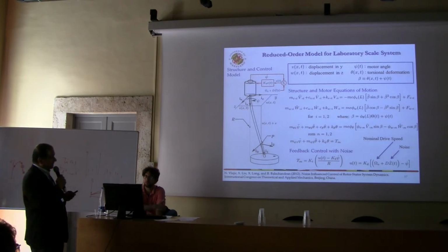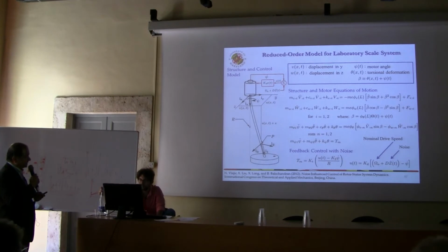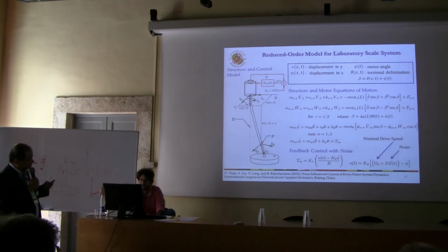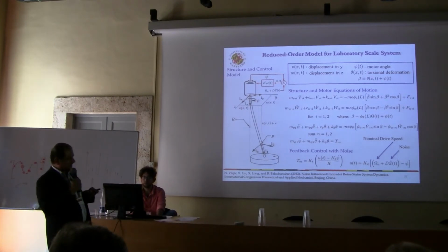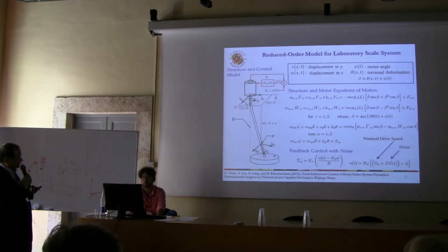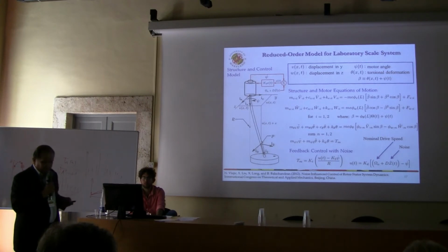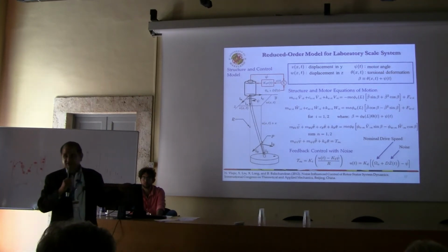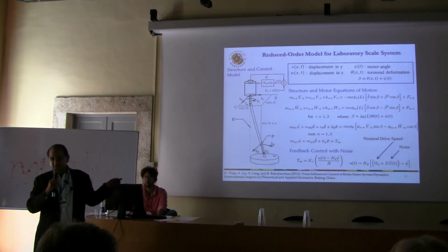And then we did a model for the system. Essentially, this is a projection on three directions. One is the two transverse displacements, and the other is the torsional state, theta, up in the top. And then the feedback control with noise is captured out here, and the delay is also captured in this case. So essentially, integrating the system is a little tricky. Because you have noise, when noise is present, you use an Euler-Maruyama scheme.